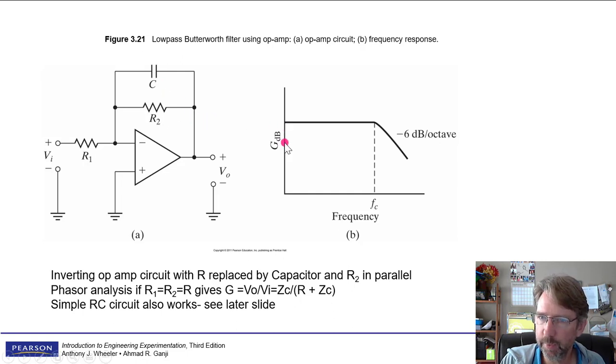So the frequency response here is shown. So again, frequency and gain in decibels is traditional. So roughly gain of 1, and then at the corner frequency it gets rolled off. We reduce all the high frequency amplitudes here, and the slope of this line is 6 decibels per octave. So these are both log scales because we have decibels here and a log scale there to make this look like a straight line.